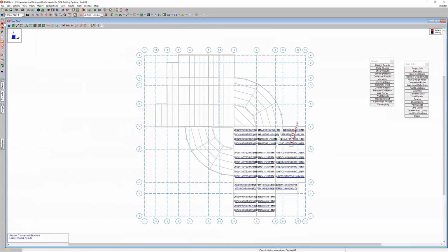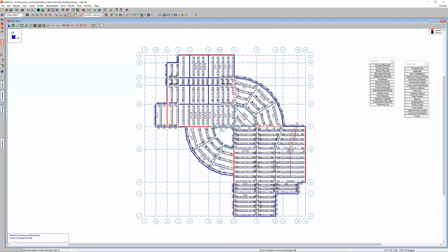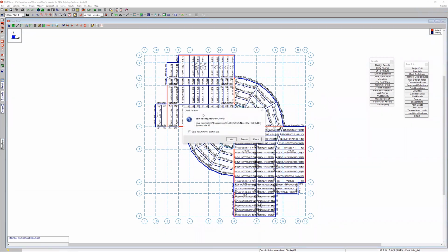Now, I'm going to go ahead and re-enable everything here. And so let's go ahead and turn off our load. Now we have our analysis done. Now let's go ahead and transfer this RISA floor model then into RISA 3D. So I'm going to go ahead up into our director and choose RISA 3D. I'm using the director, so it's just asking me to save the file, so that's fine.